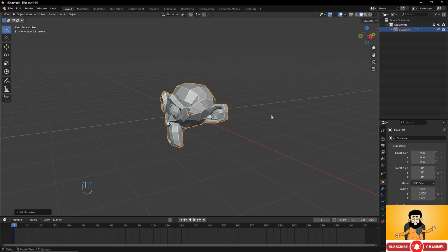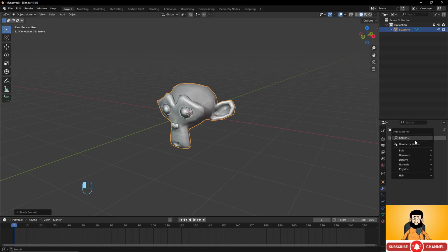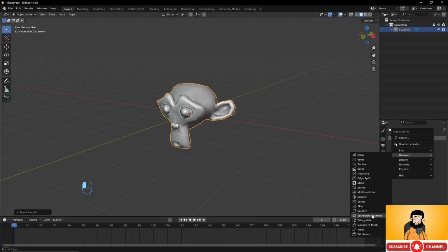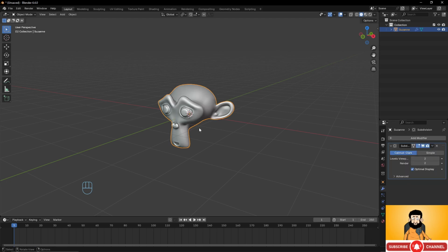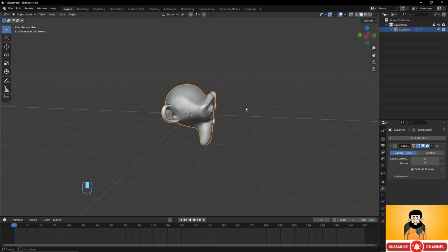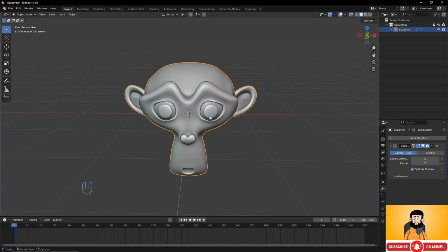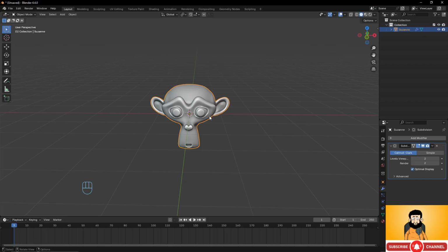It's the object of Blender. So to make it more beautiful, we'll make a shade smooth here and add a modifier, generate, subdivision surface with 2 here like that. We will learn all of that after, but it's just to have a nice object to manage here and turn around, and I will show you how to do that.